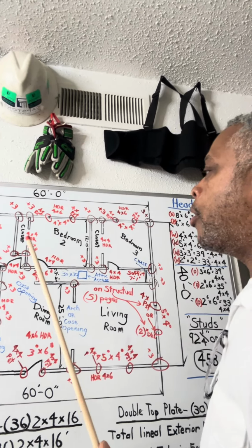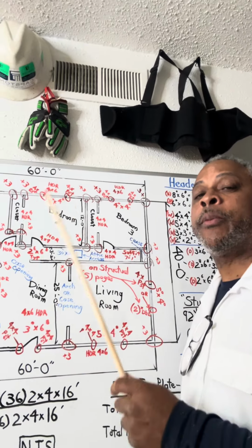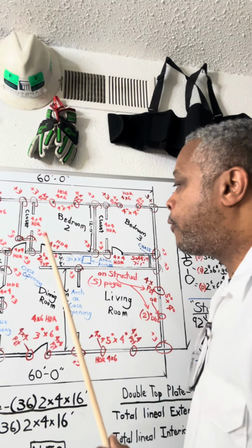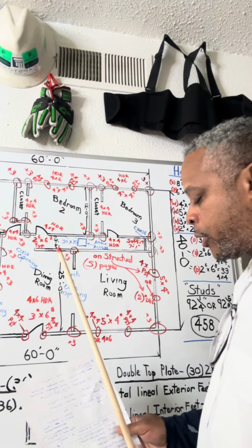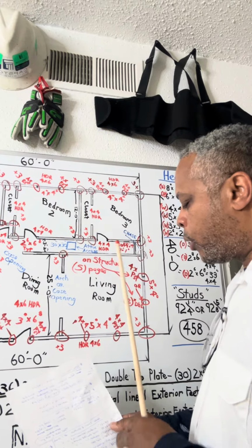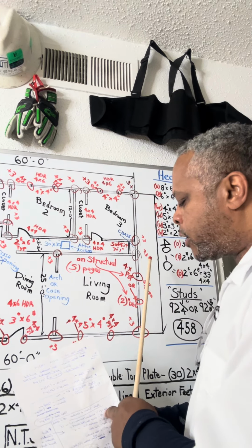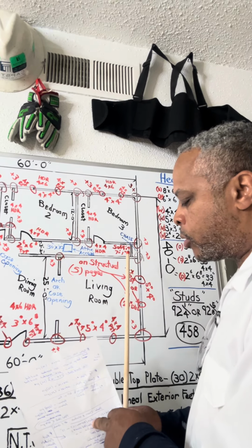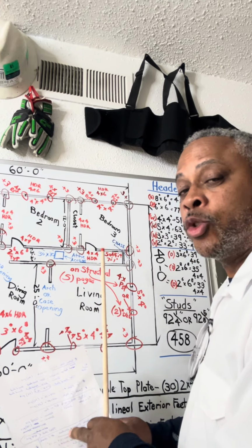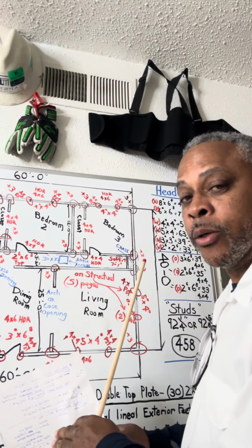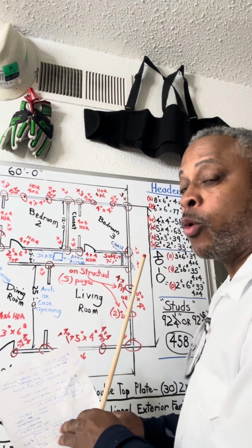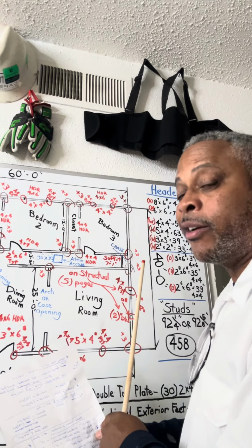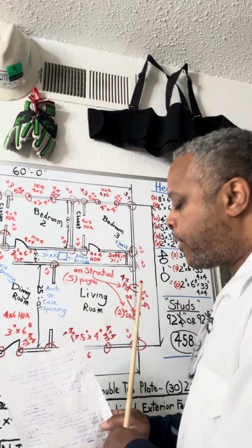Okay? So all these headers need to be calculated up. You separate your 4x4s and your 4x6s. You calculate every size that you have. There are 13 of them. When it all boils down, I have three 4x6 by 51. That's the windows for bedrooms 1, 2, and 3. Then the closet in bedroom 1: itemize that. That's 101 inches, which is 8'5".